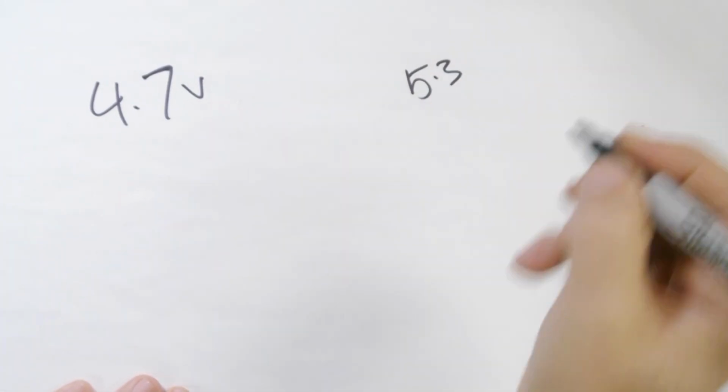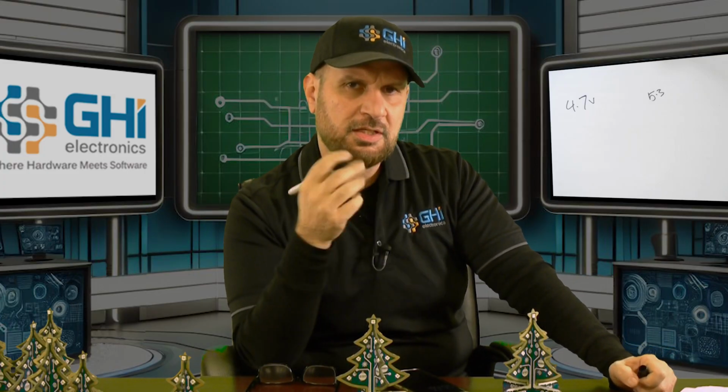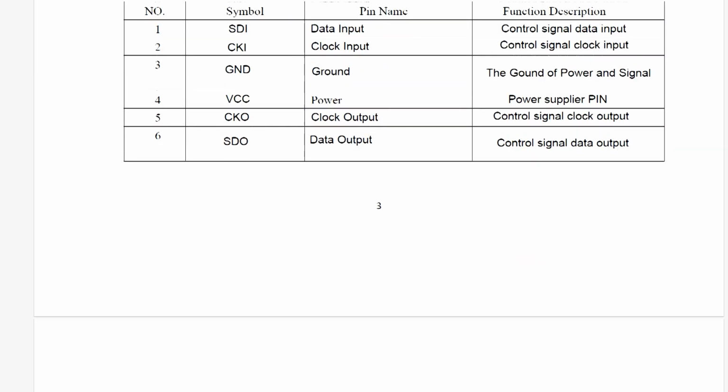Now looking at the data sheet of the LED, just to make sure that we are within voltage, the LEDs work up to 5.3 volts. So 5.3 volts is okay for the LEDs, but we're giving them 5 volts and they would not work. Why is that? There seemed to be magic happening at 4.7 volts. I went back to the data sheet and started checking what voltage levels are expected by the LED.